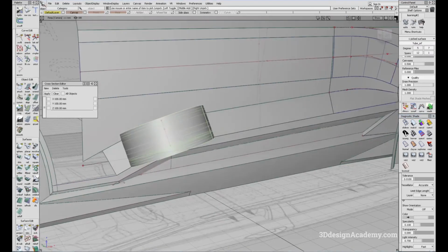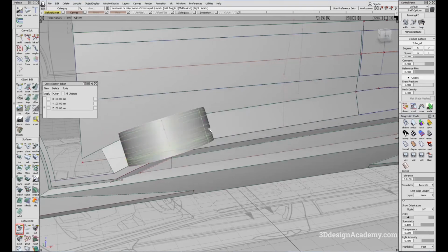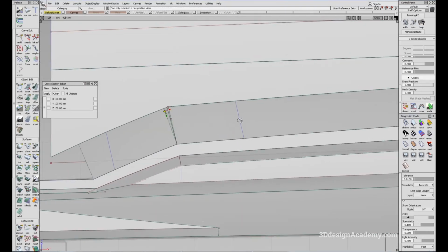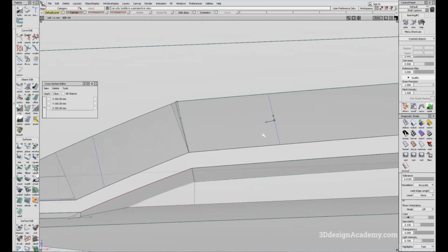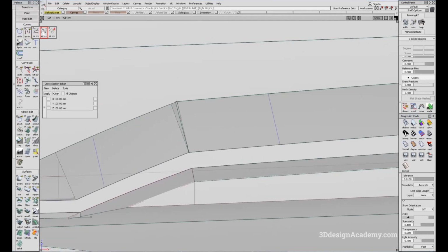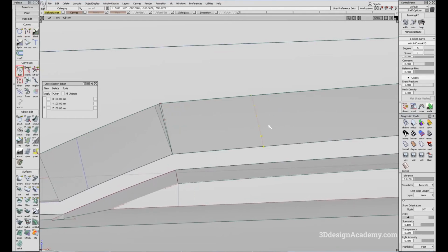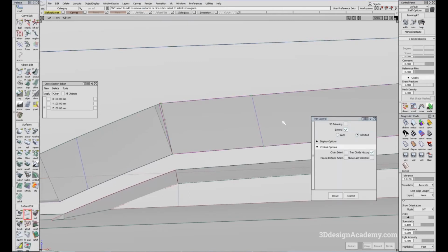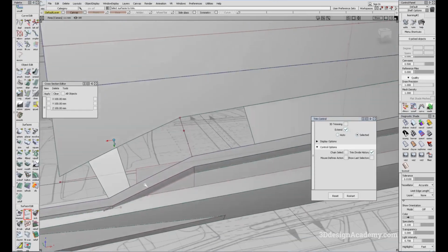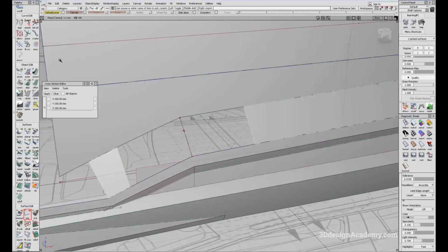And I'm going to grab this one, and I'm going to do an intersect with the surface. I'm going to delete this tubular offset. Now, the problem with using a tubular offset is that sometimes it does create a lot of spans. I'm going to guess that this curved surface is actually quite, oh, actually it's pretty clean. So in that case, I'm just going to delete or trim. Okay, so now we have the two edges.